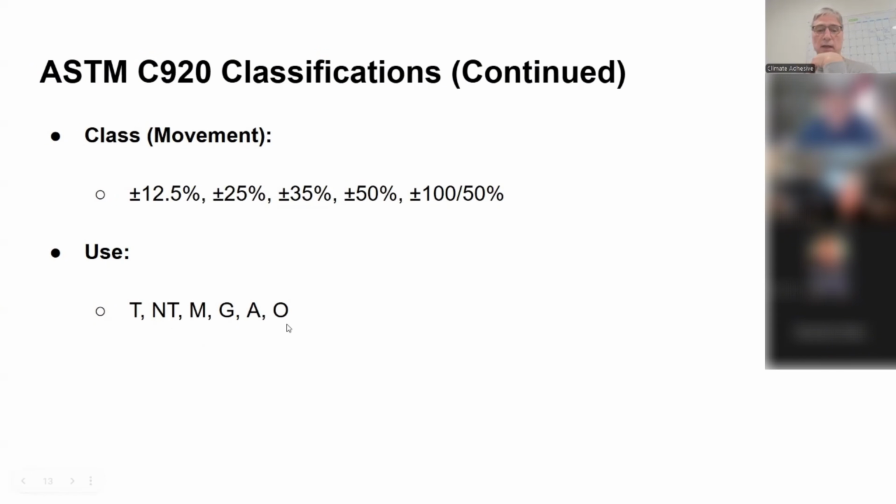You determine whether or not it can be used in traffic applications based on what's called Shore A hardness, which I don't have on here. If it's above, I believe it's 25 Shore A hardness, then it can be used for traffic applications.